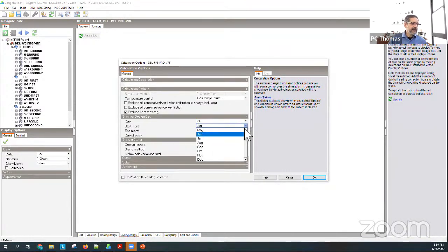The other thing I'm going to do is do the calculation for every month from January to December, because we've got the data, we might as well cycle through. Typically, most consultants will do it for the summer period, so they may say May to July or August. But sometimes, depending on the mass, the glass, the shading, the insulation, you will have some zones peaking in some odd months, okay? So it's good to have a calculation that does every month.